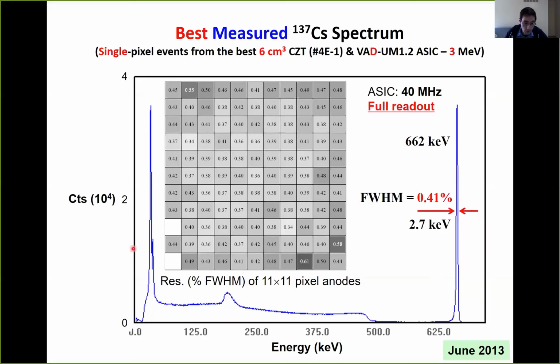And these are the two X-rays you constructed. And you can see here that this is a 0.41% energy resolution, so about 2.7 keV. And there is the noise associated. The reason why it's not what we want, a delta, is because of two things. One, it's electronic noise, which is actually the major noise contribution to this detector. And it's also poor detector performance.